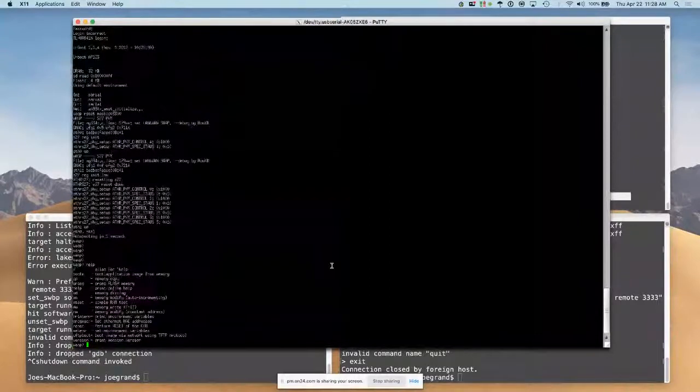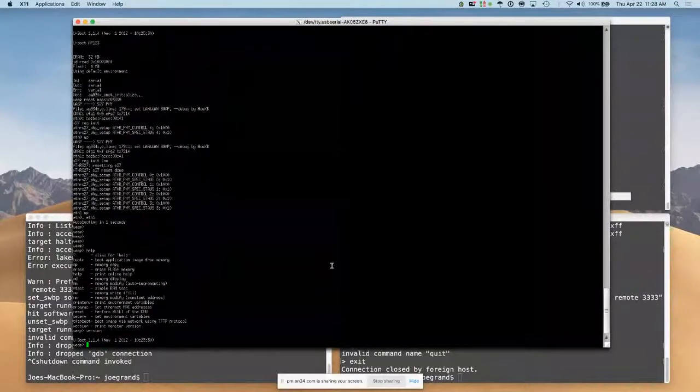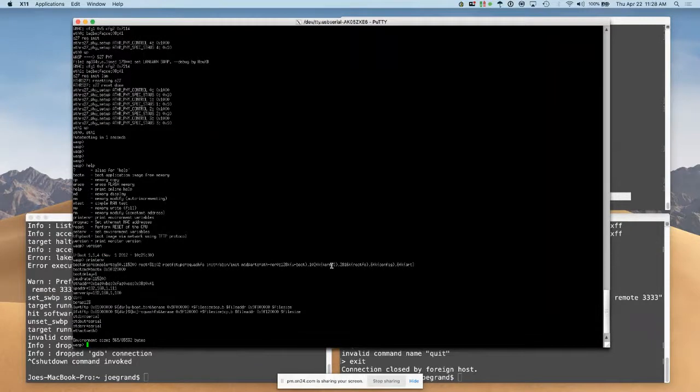From here, there's a whole bunch of commands. We can, let's see, get version information. We're in U-Boot. We can print the environment variables. So these are things that are going to be called as the system's loading. Maybe there's going to be interesting information here. Ethernet address, we see, oh, there's TFTP as well. So TFTP boot. We can actually use the